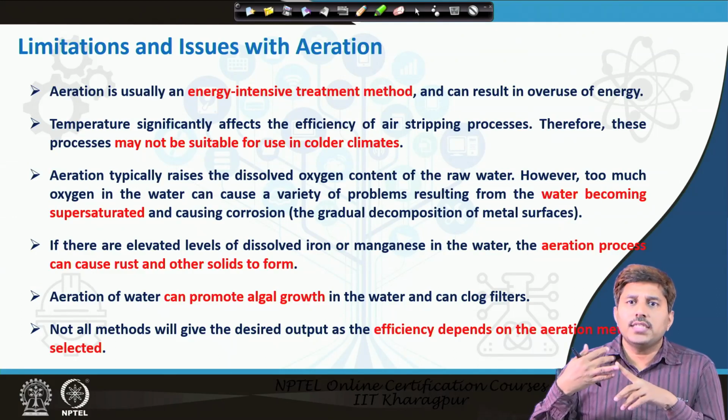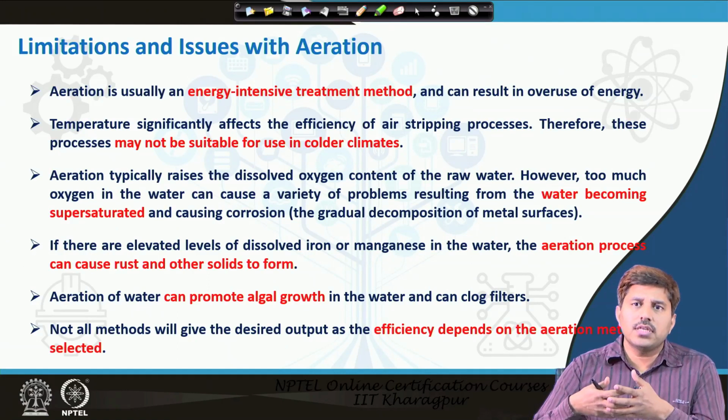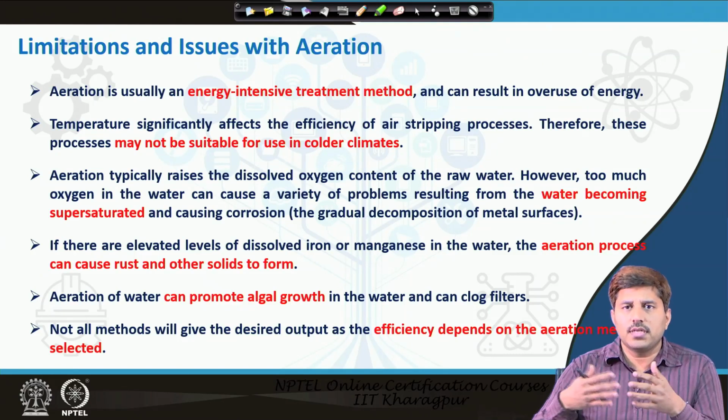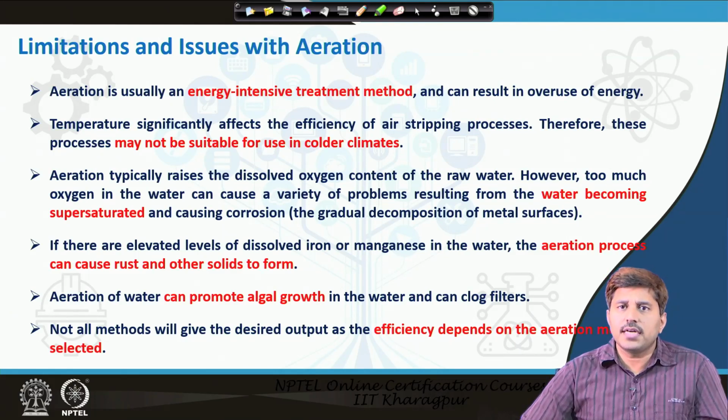Otherwise, if you are abstracting water from a surface water source which already has an adequate amount of dissolved oxygen, why go for unnecessary aeration? So, aeration may not be provided for surface water sources. Groundwater has a relatively stronger case, but that also is recommended only when there are problematic components present. If not, then we can even avoid aeration for groundwater sources, and maybe some pH control and those kinds of things can be used. The second thing is that there are chemical or other alternatives also available for aeration.